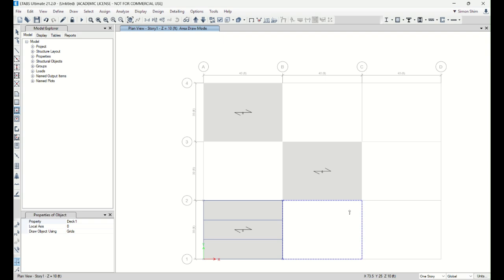But if you rotate it, it falls down. Because if your metal deck is spanning like this, the span would be this long. Our intention is this is formwork. Metal deck has this geometry. You need to put this metal deck on top of a series of beams, right? Physically, when you see it, yes, it makes sense.